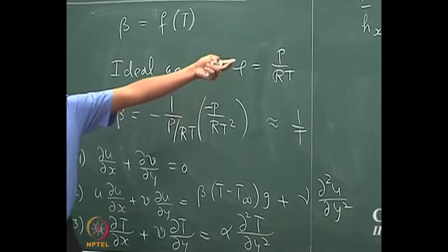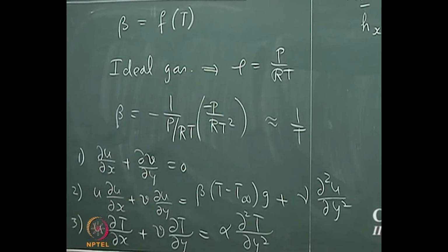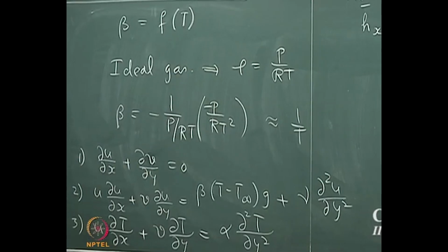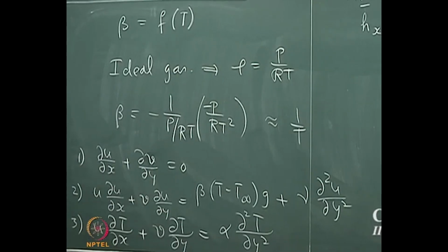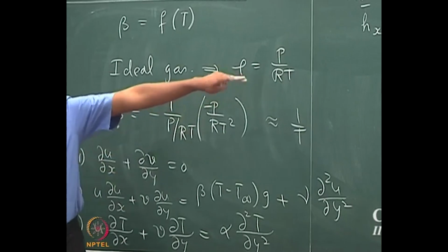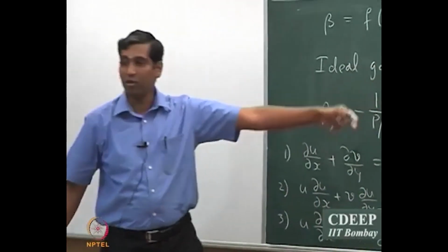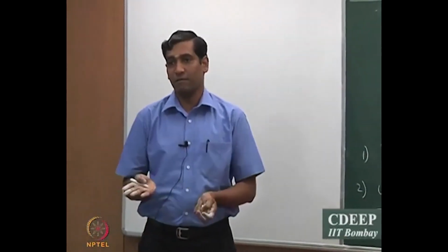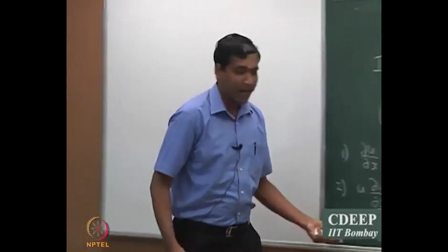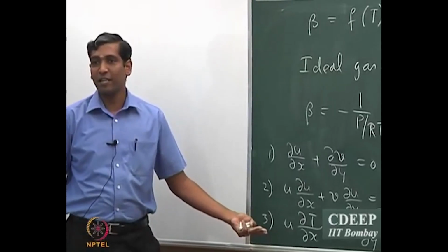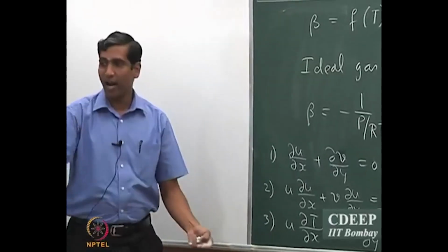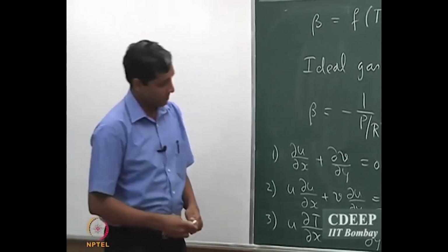Remember that if we know the gradient at the wall, we are done, right? So heat transport coefficient, because the temperature of the plate is constant and the bulk temperature is constant. So if we know the gradient at the wall, we are done. So the objective is really to find the temperature gradient at the interface between the plate and the quiescent fluid.